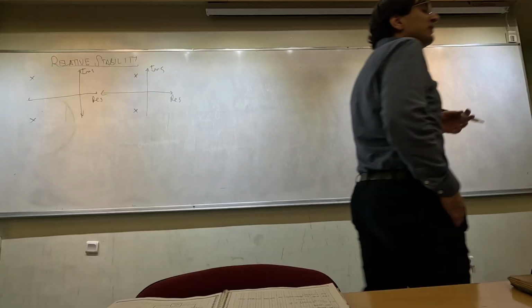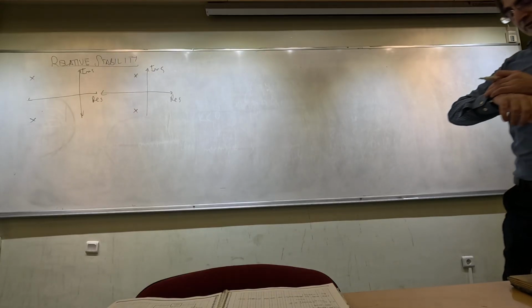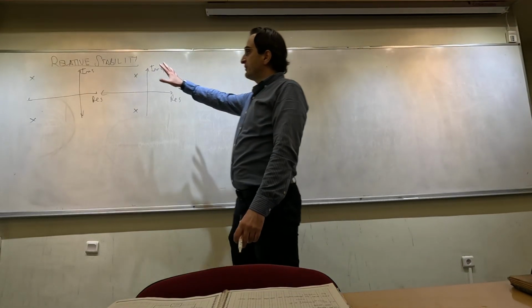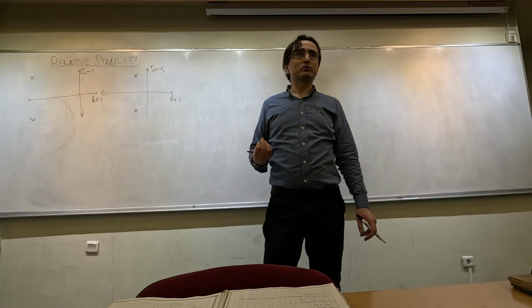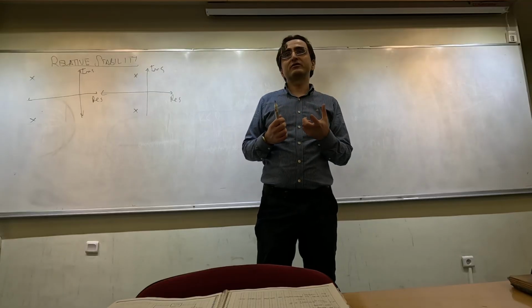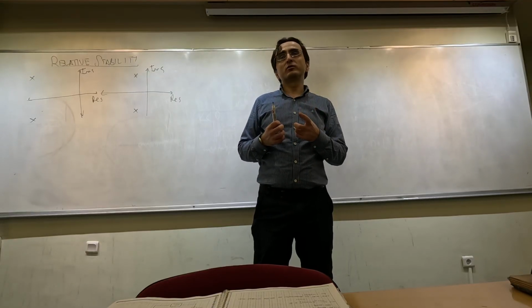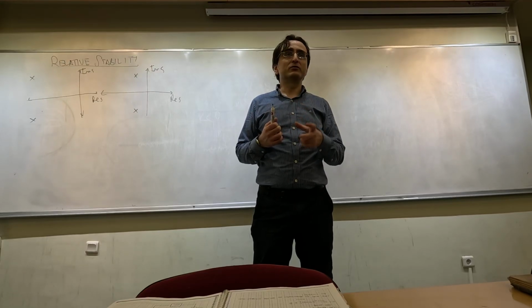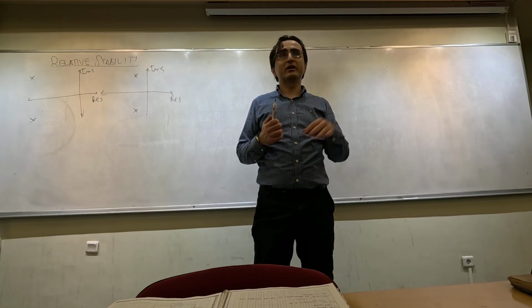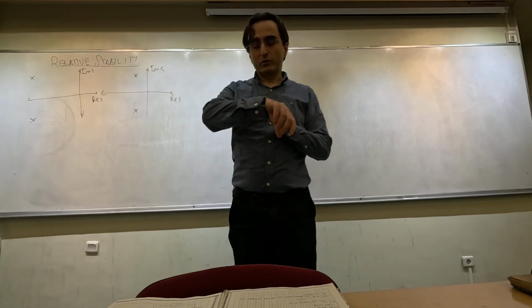Okay? We would like to do a similar thing in frequency domain. By seeing the poles of the system, I can decide how stable a closed loop system is. We will be able to do a similar thing, but now in frequency domain. Okay? And in frequency domain, we are going to be able to measure how stable a closed loop system would be. Okay? And the measures of that are going to be the gain margin and the phase margin, which we will be able to read quite easily given the Bode plot of the open loop system, which is going to be in the second hour.